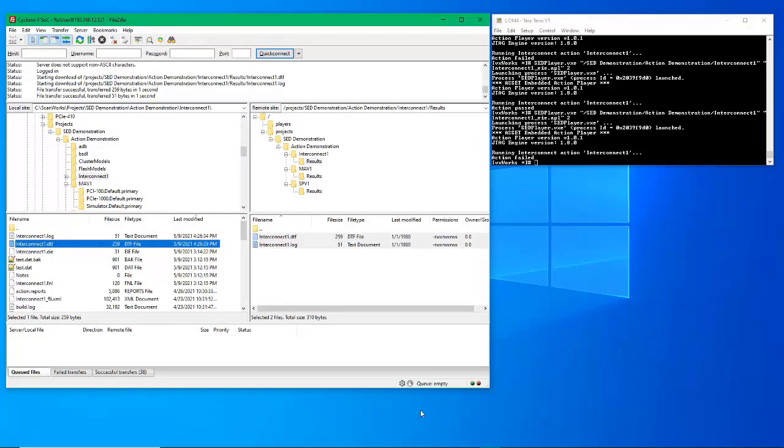Okay, so we'll take a little different step here. We need to diagnose the actual fault. What took place when the interconnect action was run? There's a command in ScanWorks, and some of you may be aware of it. You may have seen it. It's called swdiagnose. We're going to run the swdiagnose command on the DTF file, and that will tell us exactly what the fault was, what occurred.